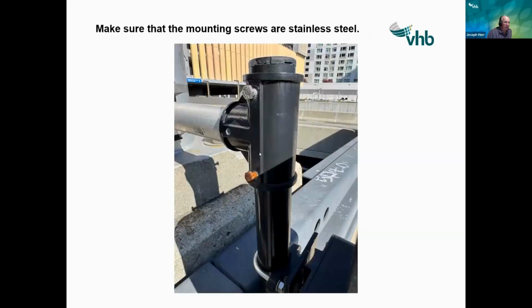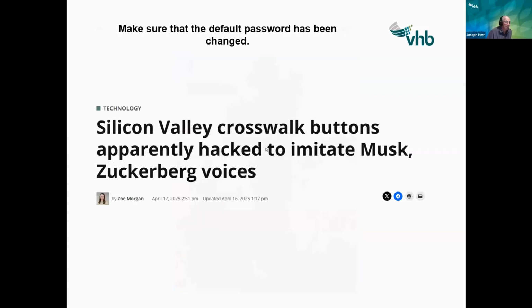You also want to make sure the mounting screws are stainless steel. This one's already starting to rust. We also have a missing screw here. This is stainless. You want to make sure whatever hardware is used is made for outside applications.